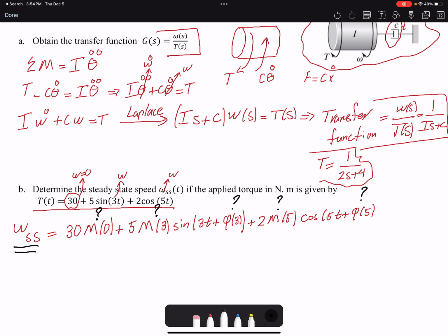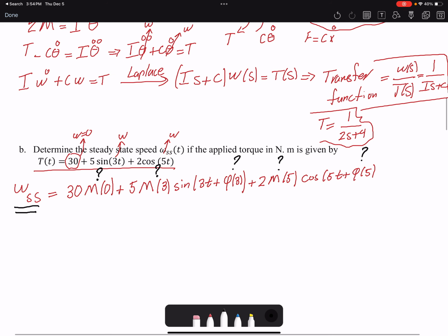So we have the transfer function. We can find this change in amplitude. Or simply you need to replace the s in the transfer function with j omega. Here we have 3 different j omega, so we're going to replace it with 3 different values. You need to pay attention to that. So I can start with M0.